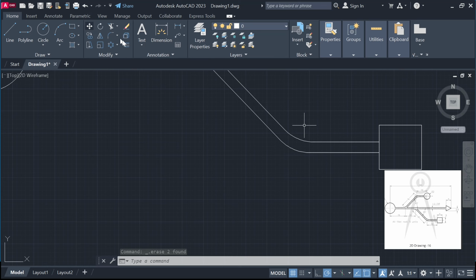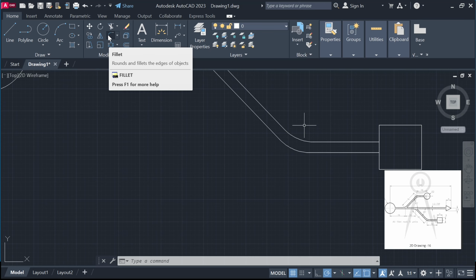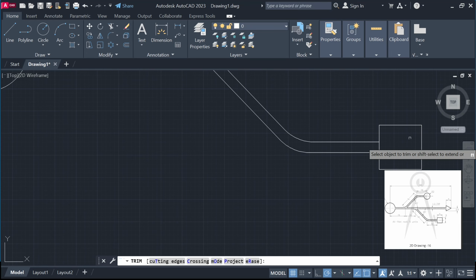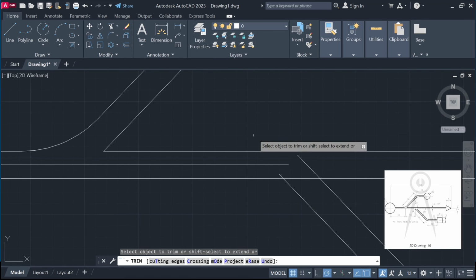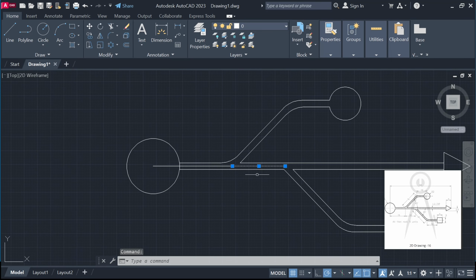Sorry, extend doesn't work if the line you are extending will not intersect with another line. The condition for extend to work is that the extended line must have a line it would intersect with, else what you're doing is trying to extend it to infinity. It might be possible, but it's just going to consume your CPU, so I'm sure that function was disabled for your own good.